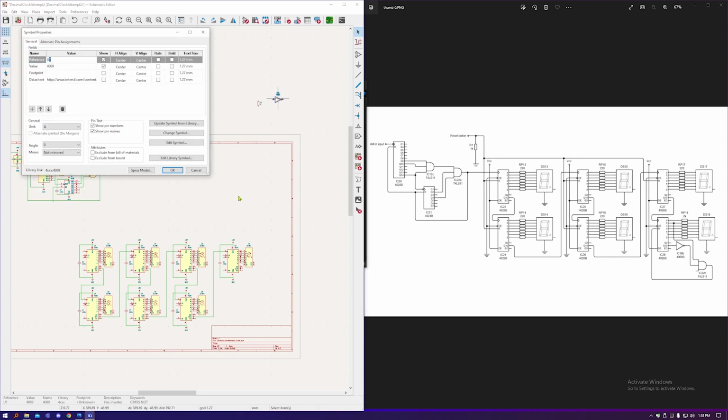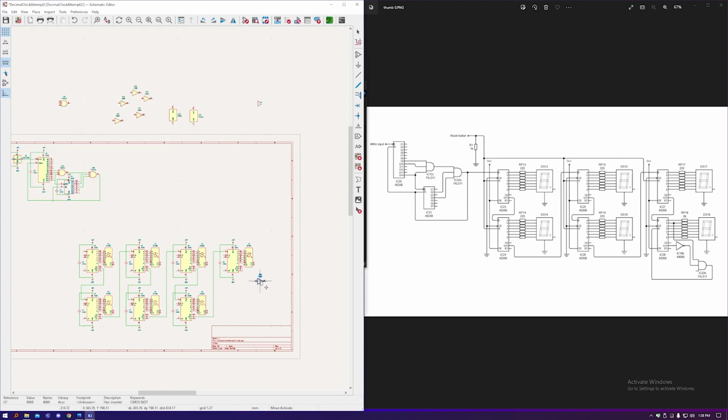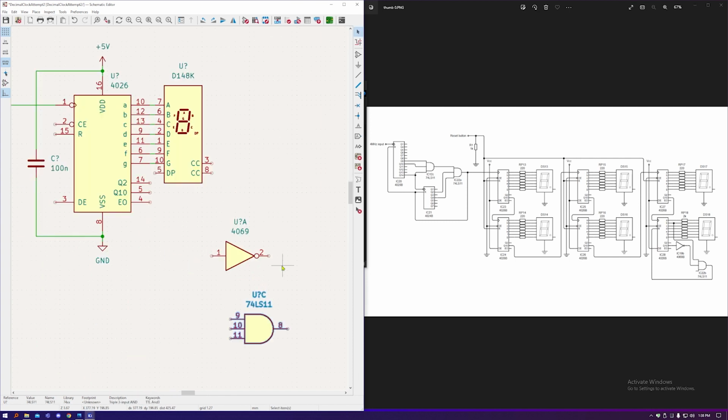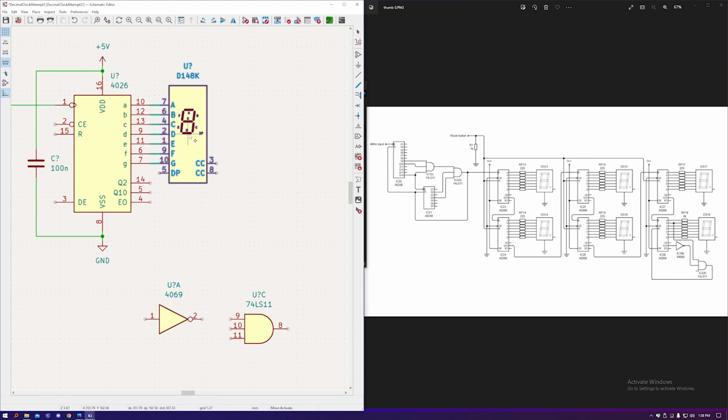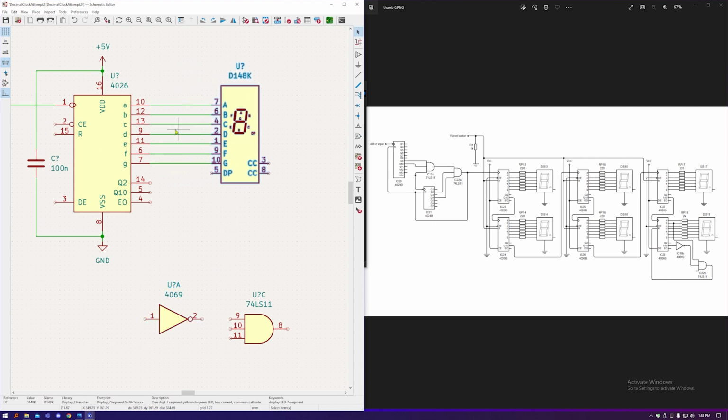So let's bring down the inverter that we need and the final AND gate. And we need to get to the output B, so I'm going to drag this away a bit for now. I'll bring it closer once we're done. Click on this, add a wire, because with these there's a circle and the circle automatically selects the add a wire pin tool. But here there isn't one, so add a wire, click on here, I'm going to bring it down, and this wants to go to the AND gate, so let's just end it there for now.